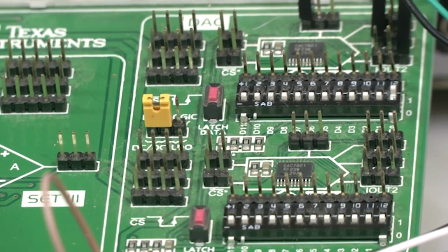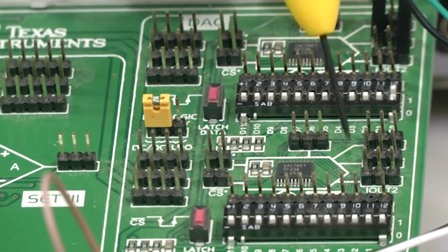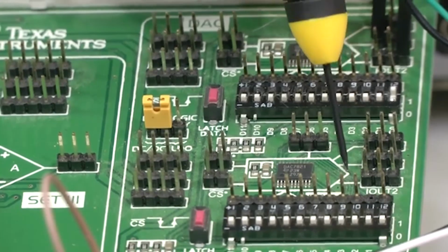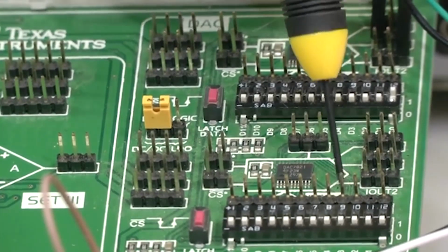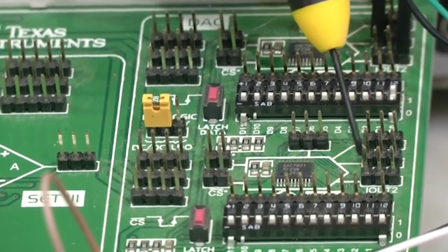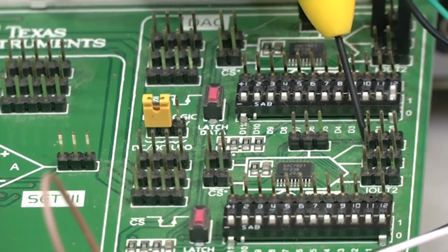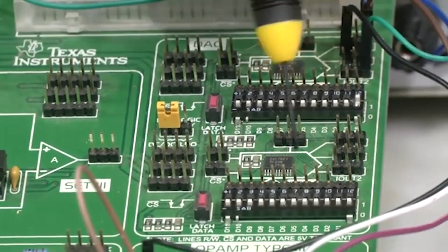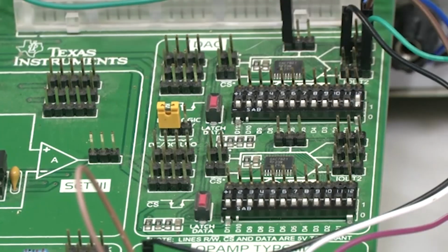The same supply we will be giving to the reference voltage, which is here, if you can see. Then the other 3 main lines are the output and the feedback resistor. So, this line is I out 2, this line is I out 1, and this line is the R feedback. What is the importance of R feedback, I out 1, and I out 2, we have covered just now when we did the circuit design.